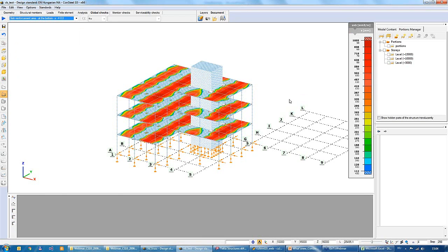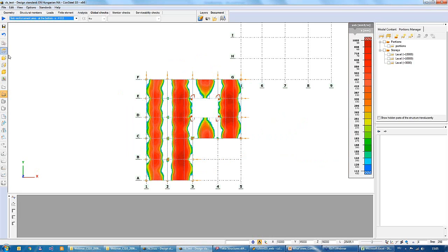In case of reinforcement design, we use the discrete color legend visualization, and in this case, in the color legend, we can see two pieces of information about the calculations. The first one is the necessary reinforcement in the selected direction in square millimeter per meter, and the second one is the necessary distance between the rebars with the previously selected diameters. For example, it's 8 millimeters. So here you can see the selected rebars.